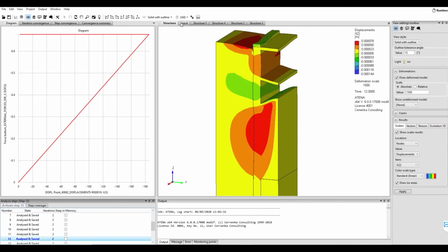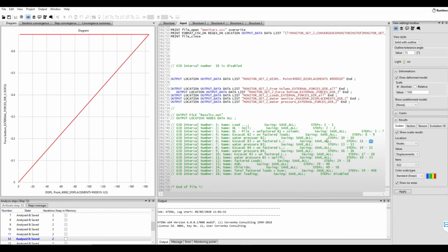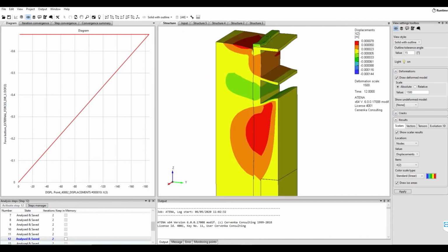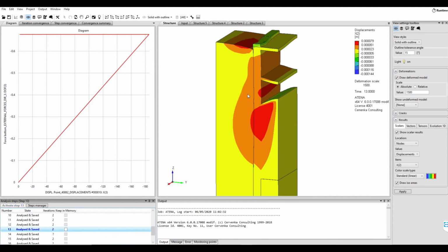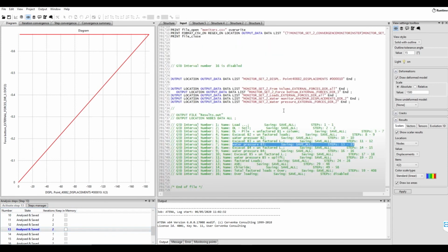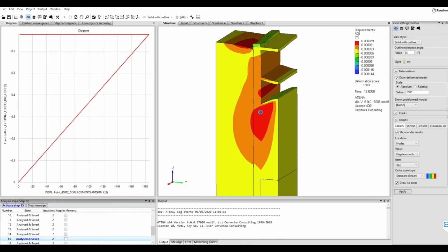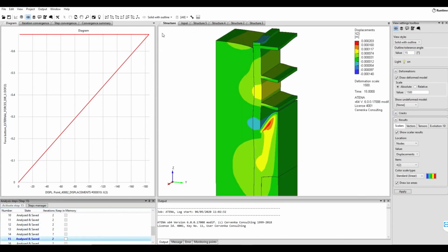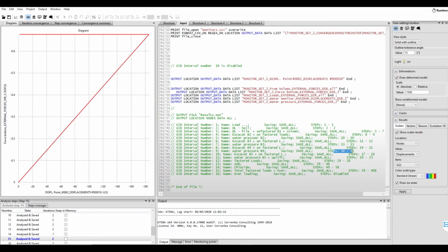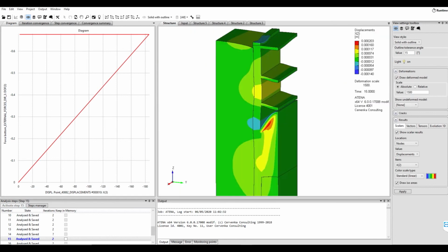We can see now the water pressure applied afterwards on the opposite side, in step 13. If we go to step 13 to see the effect, now the effect will be more clear. You can see then we excavate and build beam P4, finishing in step 15. Let's go to step 15. After that, the water pressure will be applied in step 16 behind the wall.